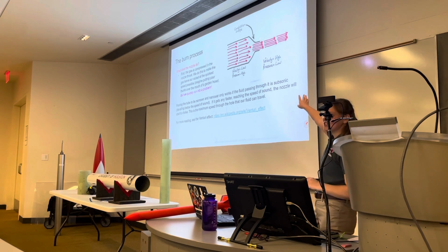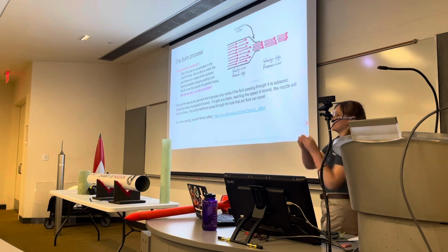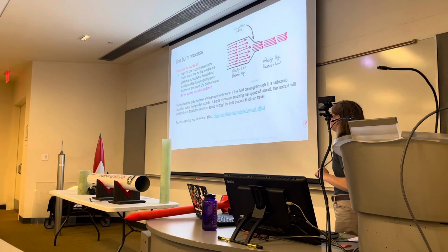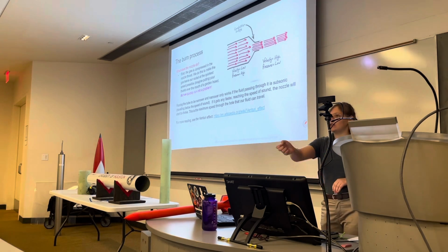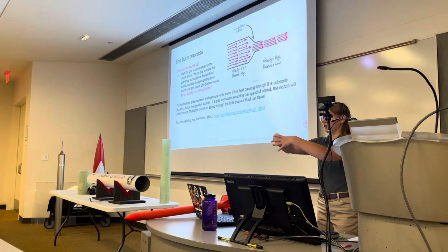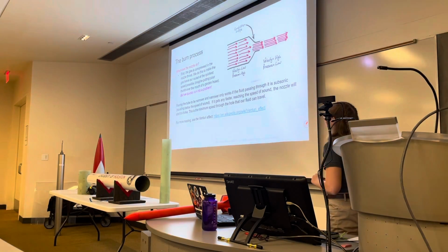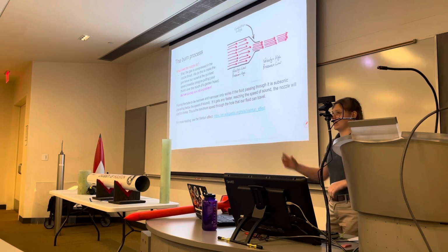Mom!" Okay, same concept is going on here in our rocket. We're squeezing the tip so that it compresses all the gas and it goes out way faster than if we just left it all open. So that works to a certain extent, right? But if you also think back to your hose example, there's a certain point where you can't really get it to go any farther, right? You've reached the limit. You can keep making it tighter, but it's really only going to go so far. What that means when that happens is that you hit the limit and you've choked your nozzle, or in this case, your garden hose.